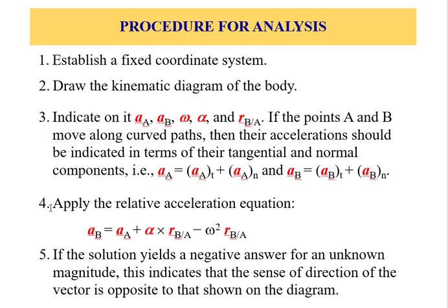So the procedure for analysis, just to summarize what I have said: you draw the kinematic diagram, label all the parameters that concern each link, and then apply the relative acceleration equation.